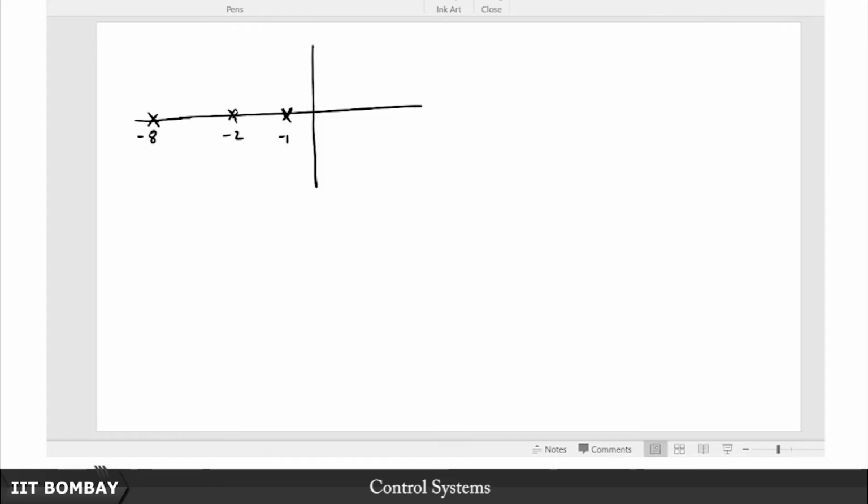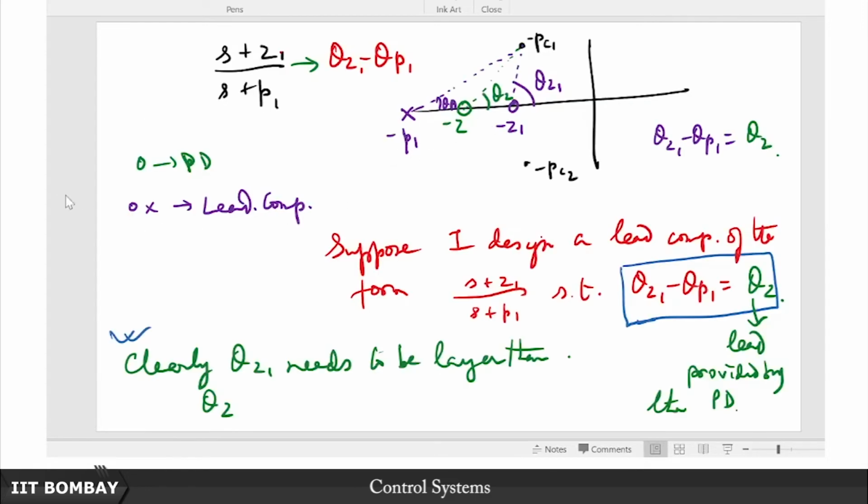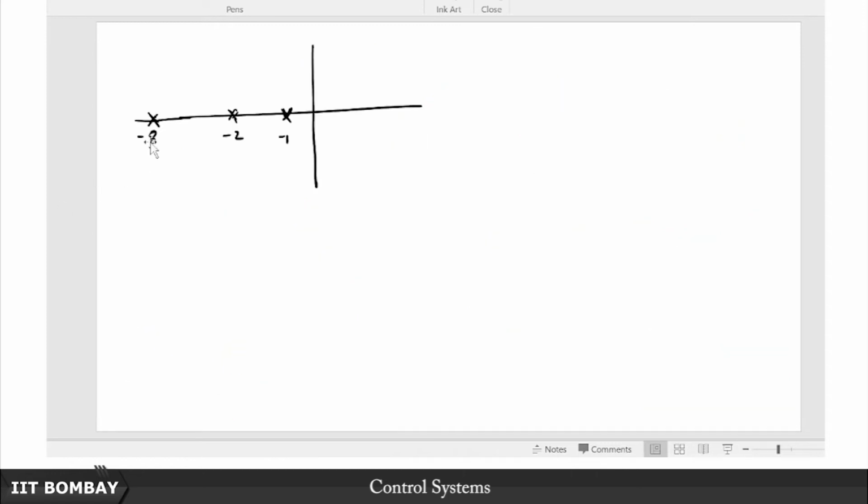That is very important, because if you had dropped this third pole from consideration, you would have drawn the root locus incorrectly and been completely off in your analysis. Only after finding the desired closed loop poles do you figure out where the third pole has migrated to. If it meets the 5 times dominant pole criteria or is nullified by some zero, then you can rest easy.